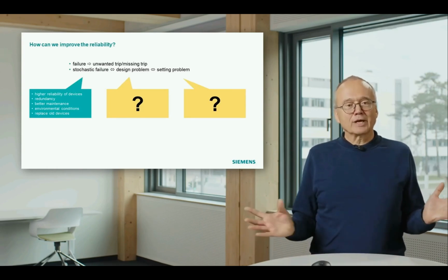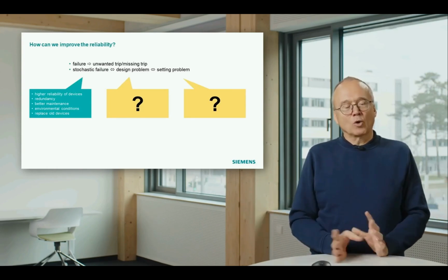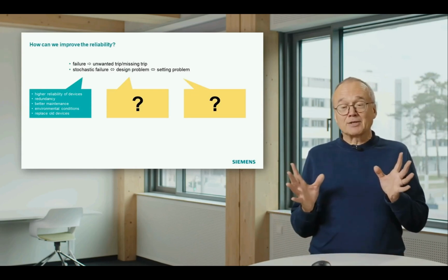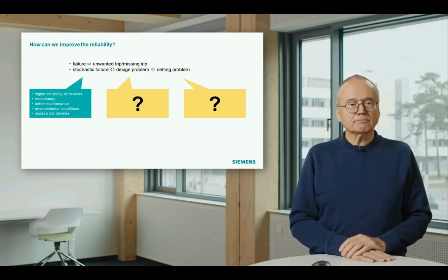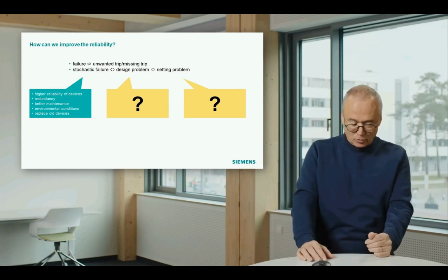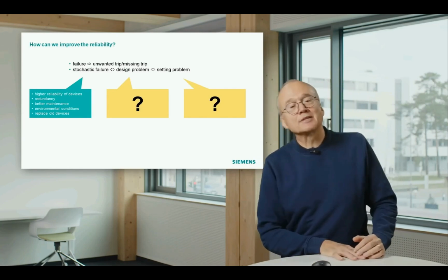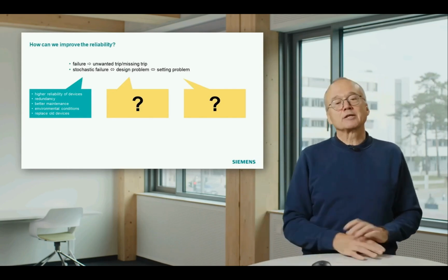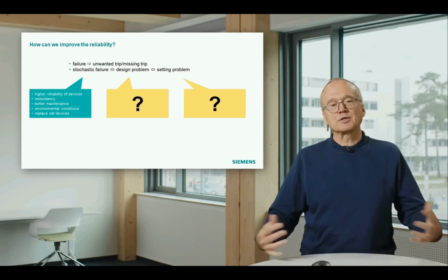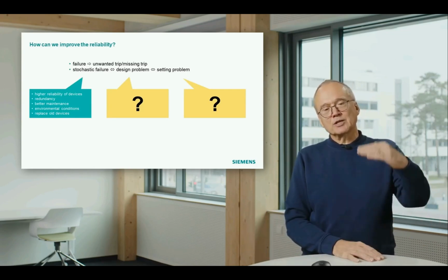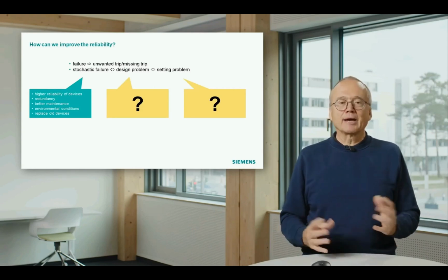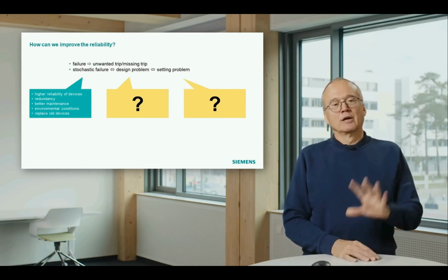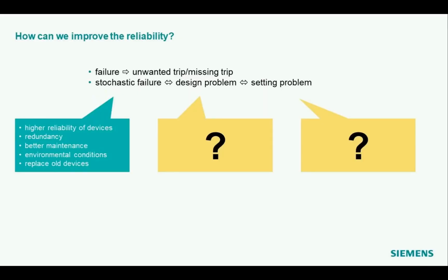And you have to take that into account, or you have to think about, does it make sense to install the relays in a better place? And the last thing I mentioned here is the question, how long do you keep relays in operation? Do you do preventive replacement with a certain concept if the relays reach a certain age, or do you just wait until they fail? Also there, different concepts are in work.